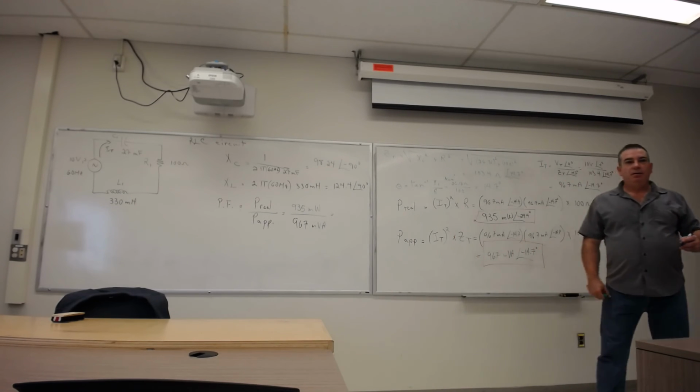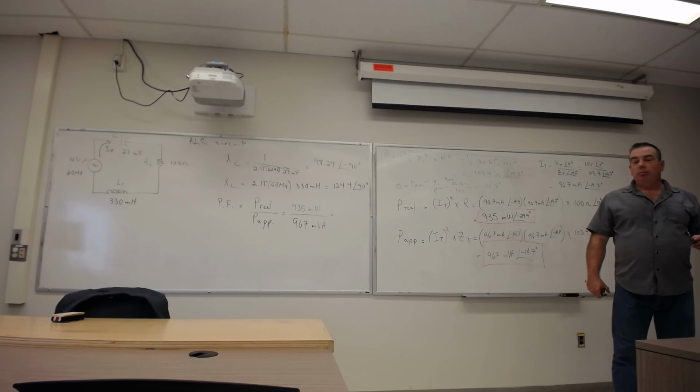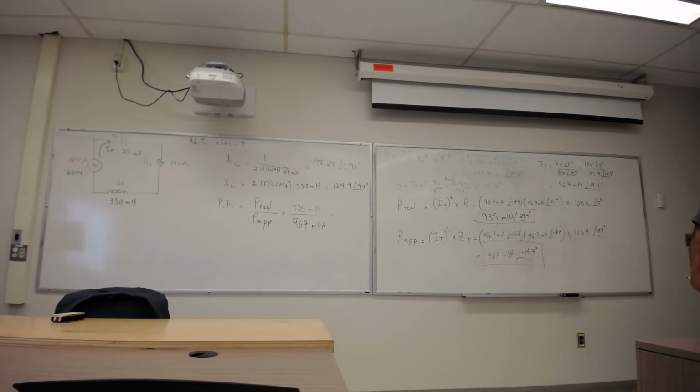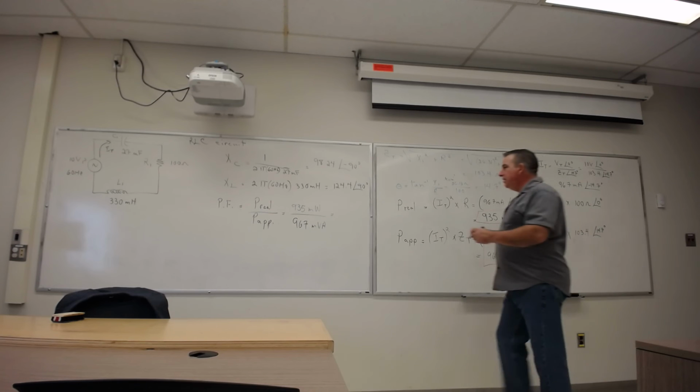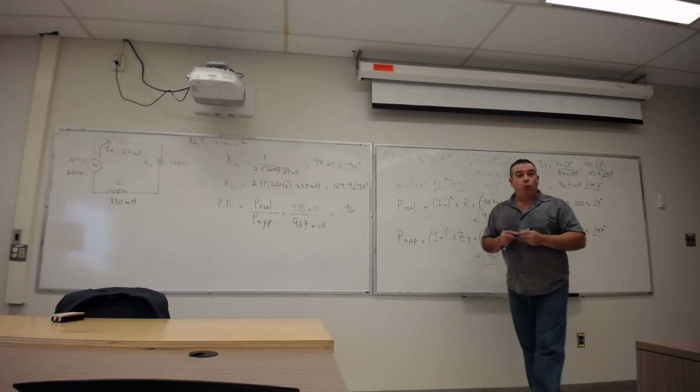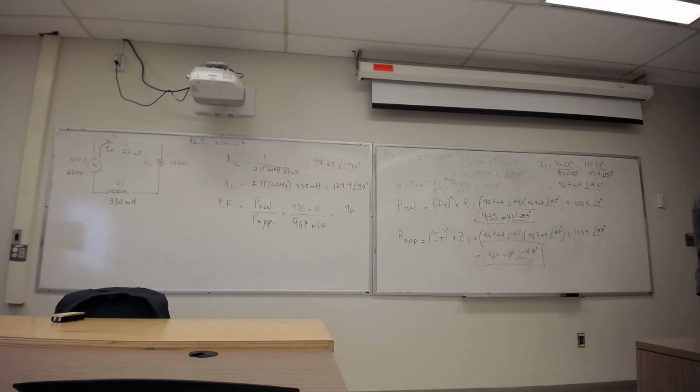Do you still need the angles for this one? No. These power factors are strictly a ratio. 0.96. Which is looking good, because it's getting really close to 1. So your power factor is much improved.